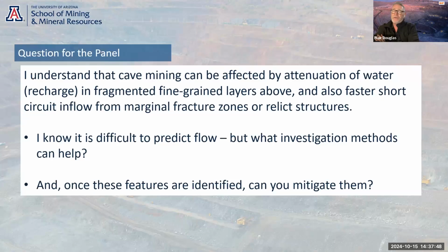I have seen packers used. I have seen grouting used to mitigate some of these larger structures and prevent inflows. But the reality is you just subside. You're basically just reducing inflows. You still have to deal with them, get the water out and get the right capacity. Not sure if anyone else has ideas around mitigation of inflows.